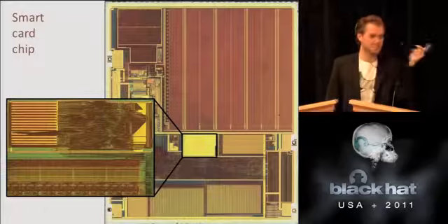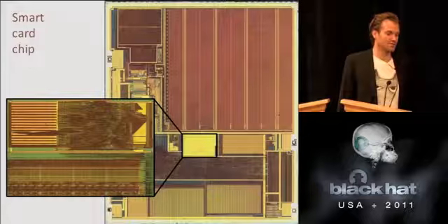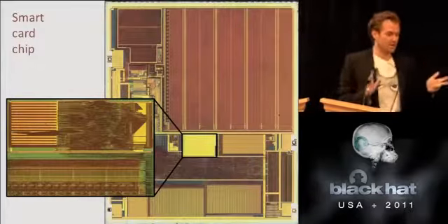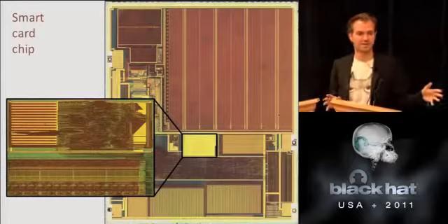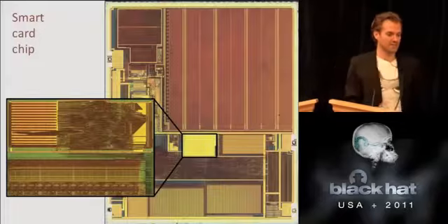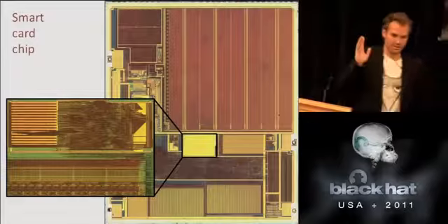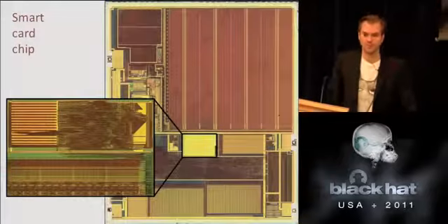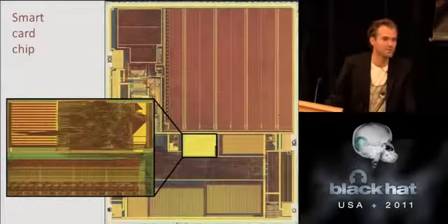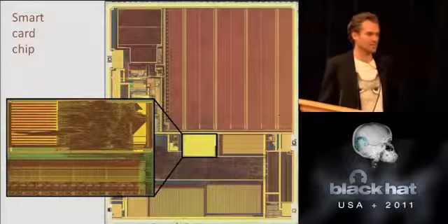And some of you may have seen his BlackHat DC talk from a year and a half ago, where he actually demonstrated how he found the 8 lines, in this case, since 8-bit architecture, on this chip, and he cuts through some structures on top with FIBs and with lasers, and then put little needles on each of these tracks. So that's the second line of attack, and the one that really for the last 10 years was the relevant one in a sense that all the chips out there were hacked using this technique.